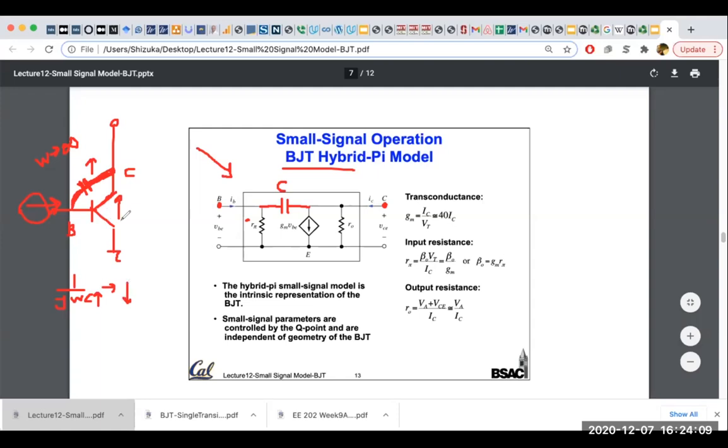So if you increase this transistor so much to increase the gain, gm, or to increase the IC, or whatever, then you think that your amplification will go high because you are increasing gm. You think that gm will increase the current. Well, yeah, it will increase the current, but now you are slowly shorting base to collector through this cap. Similarly, you have another cap here and so on. I don't want to make it more complicated.